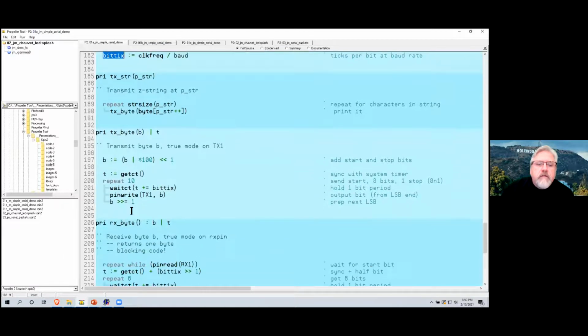So we'll pop down here because the transmit byte is the first thing that comes to attention. There's a couple of things going on in this line. You'll remember we have the data byte. We also have a stop bit and a start bit usually. And so the stop bit is going to follow our data bits and it's going to be high. So the way that we're going to do that is we're going to OR hex 100 because this is a space for our data to go. And remember, OR with 0 doesn't change anything. So this will put a 1 in the stop bit position initially.